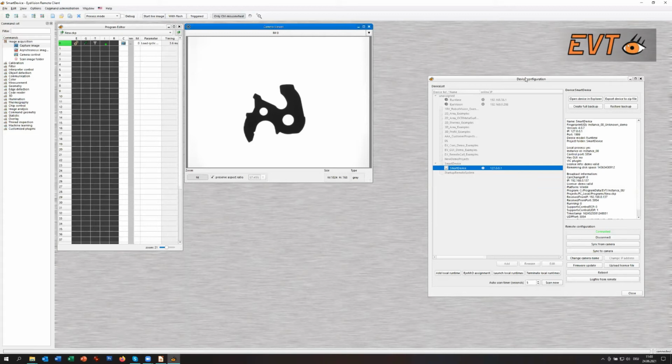If we recapitulate the list we looked at today, smart cameras with an x86 or an ARM inside, or one of the embedded systems, all of these systems are much faster than the PCs or machine vision computers used at that time. Therefore, there's no real need now, based on the CPU speed, to say I need a smart camera.